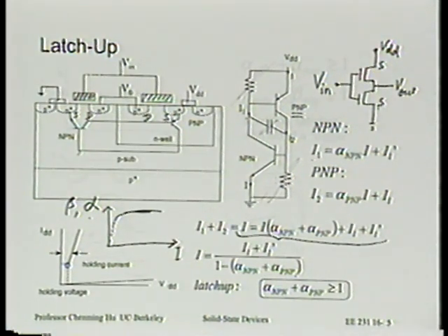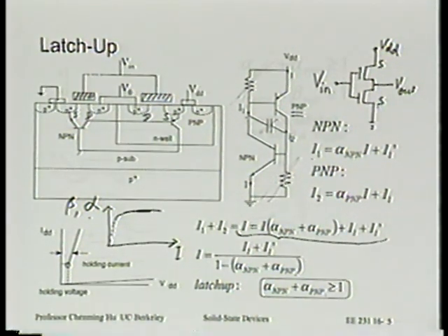Okay. So when you don't have large current to begin with, this condition is actually not satisfied. Therefore, transistors put together in series in this manner do not give you a short circuit, do not give you a latch-up. That's why normally a CMOS circuit is not in latch-up.